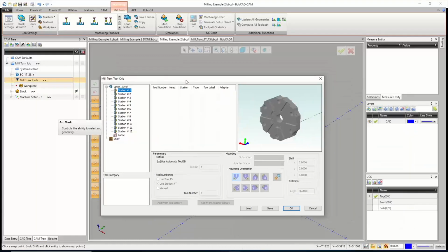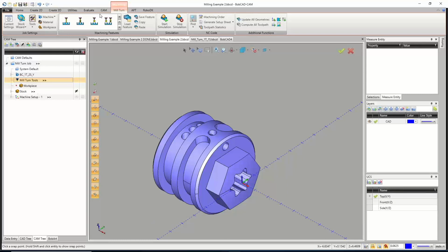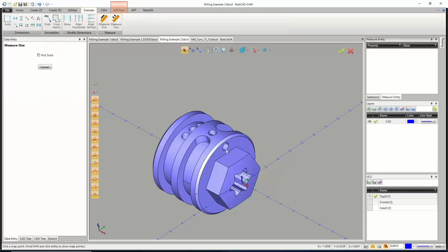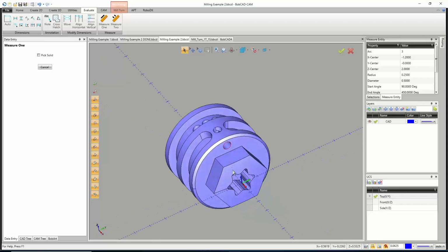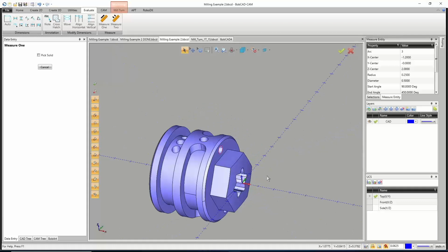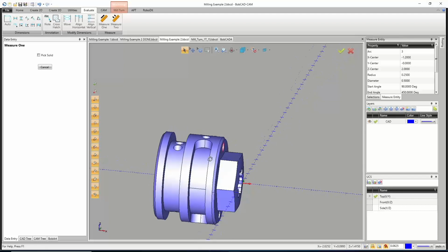So looking at this, before I set that up, let's take some measurements. I believe all the holes I have are a 1/2 inch. So even these OD ones, we need a 1/2 inch drill for the front face, the center hole right there. We also need a 1/2 inch for the cross drills out here. We're going to need a turning tool. We're going to need a grooving tool for back here. And then that's really it.